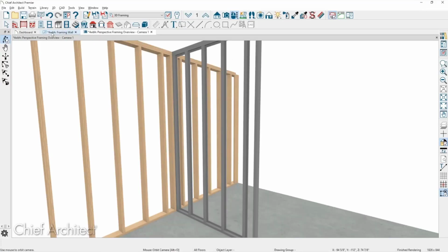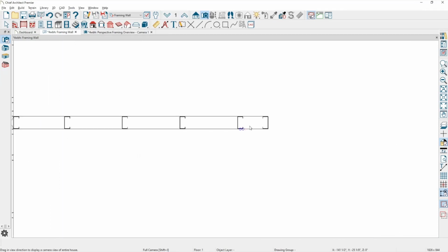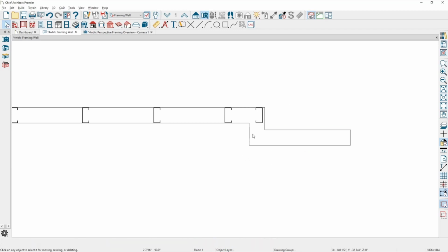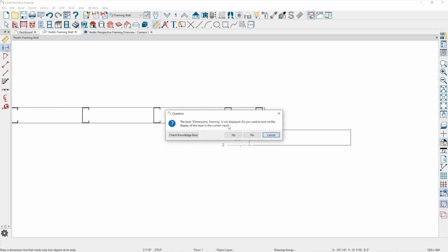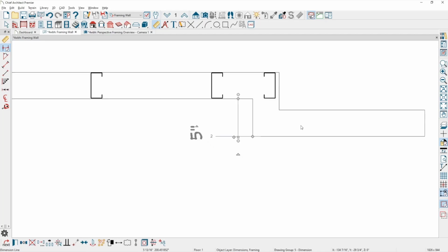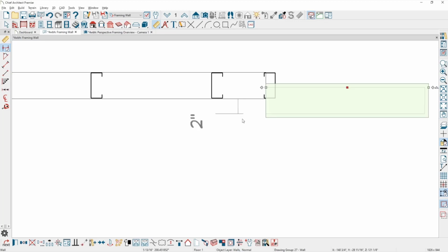Okay. So let's see. An offset in the wall, you know? Right. So in this case, you've got a small 6-inch wall or something like that, right? Yep. And it's very small. Yeah, maybe half the width of the other wall. So try making that offset like 2 inches. Yep. See, the connecting walls disappeared.